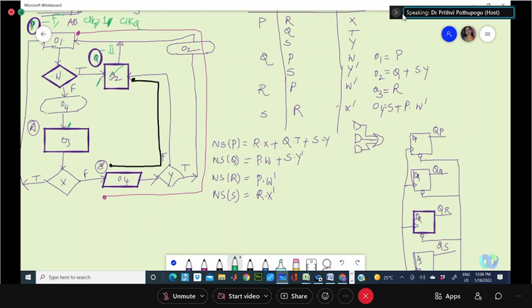See, first clock, if you apply, this is your clock P. I can take this as clock P. In this duration, when at the end of this clock P, this P state will either end at Q or end at R based on the value of your W. When W is true, it will be at Q. When W is false, it will be at R. Then that function of the clock is over.